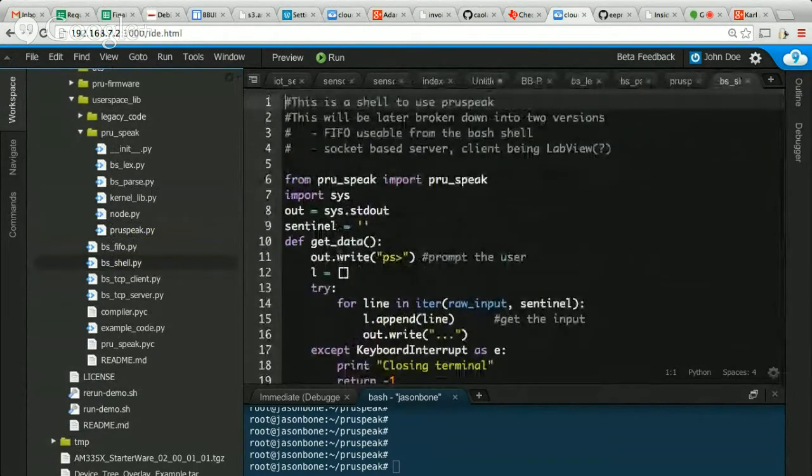And then those get called through. If you want to interface with it like a shell, you could just start this shell command, and then it'll give you a prompt here that you can type commands into individually. If you want to start a script, there are some keywords reserved for starting a script. You type in script on one line, then several different commands, then script again, and then you can type in run to actually run the script that you've loaded.